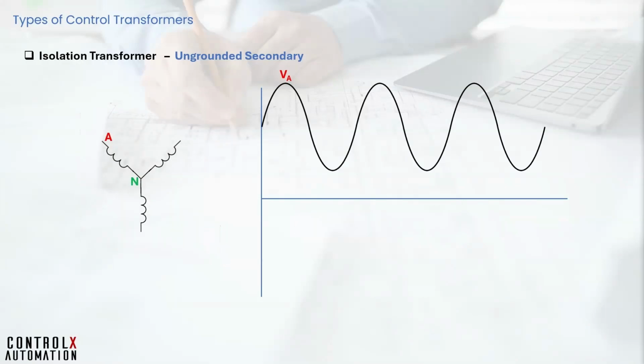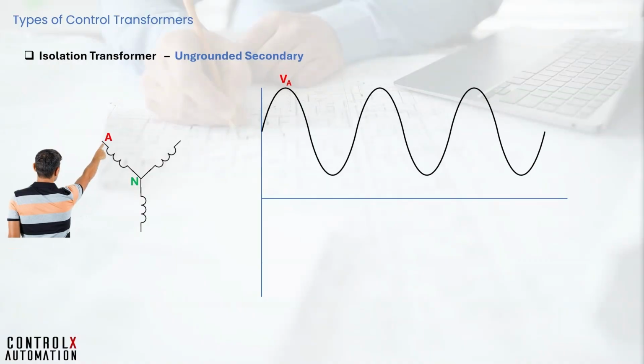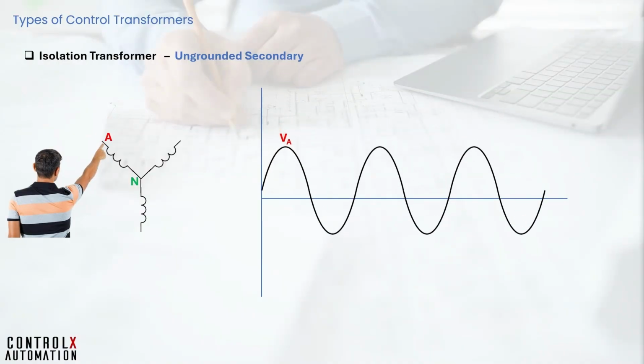A person standing on the floor is at earth potential, electrically speaking. Touching one phase does not complete the electrical circuit back to the neutral or another phase, as long as he's only in contact with one phase. When a person touches a floating phase, their body provides a low resistance path to ground, which pulls that phase voltage down. Now if you measure the RMS voltage between that phase to ground, it will be close to 0 volts. So why doesn't the person experience an electric shock?